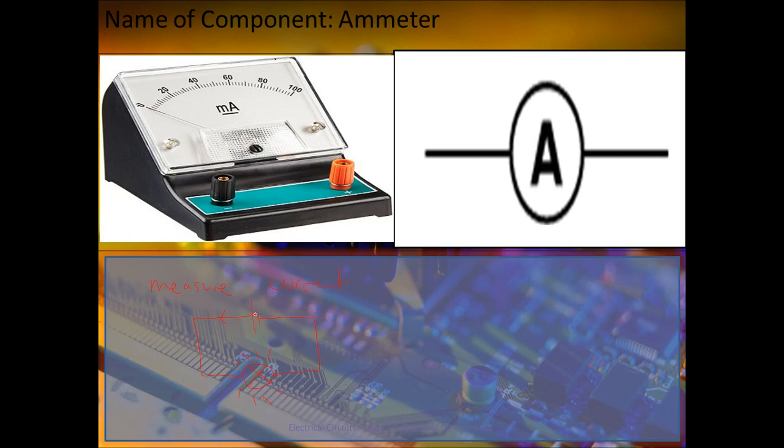Now, during that time, that current would be flowing. It's almost like an army of electrons marching. And it doesn't matter where you would position yourself, you would always be able to see the same amount of electrons. So an ammeter only needs to go at an individual point in a circuit, because if you fitted one ammeter there and you fitted another one over here, the same number of electrons would go past, and therefore they would both give the same readings. So therefore, when we do this, because it's connected in one point, we say that these go in series, and they have to be fitted in series in order to function correctly.